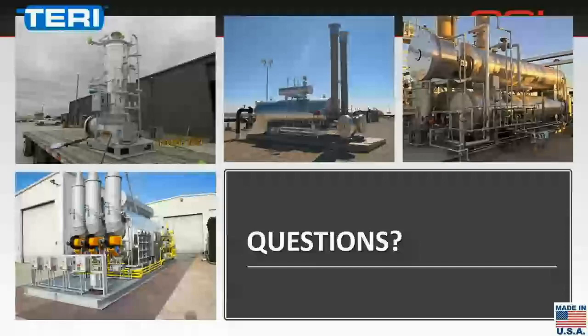What I was saying was, yeah, they very well may have different boiling points. I don't know exactly what those are, but what I will say is that generally speaking, your bath is going to be at 180 degrees. That's kind of the maximum, and that's not just an OGI standard. I feel that a lot of other manufacturers follow that. But Brad, since we don't supply the glycol, if you looked at a spec sheet on the type of glycol that you were purchasing, you may be able to see what the boiling point is. But I have a feeling that 180 wouldn't be anywhere near that boiling point.